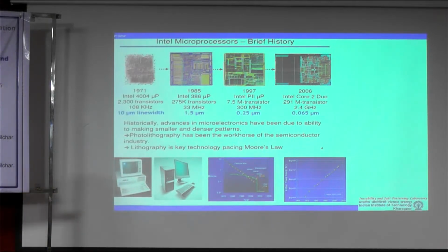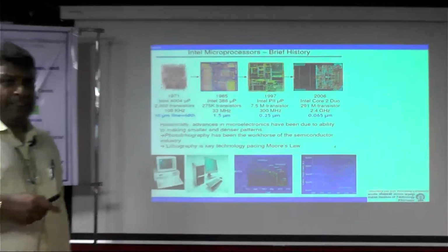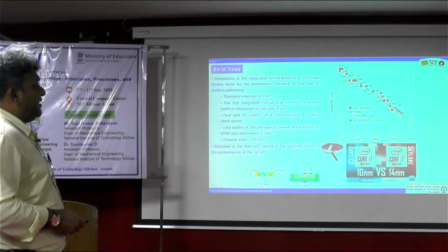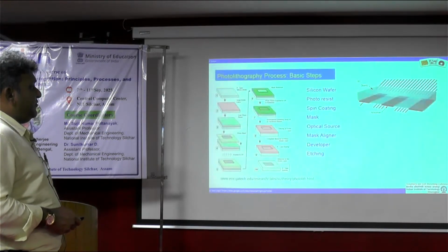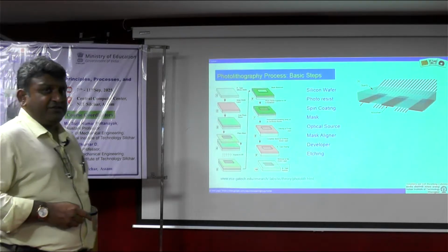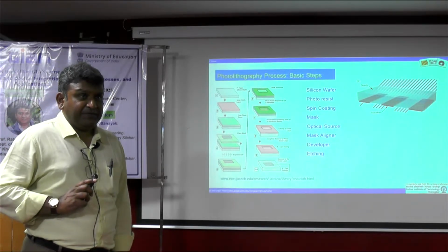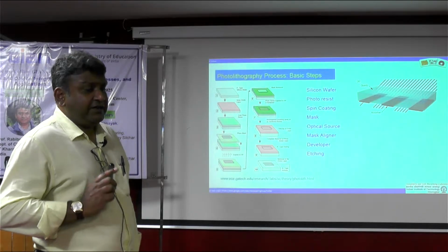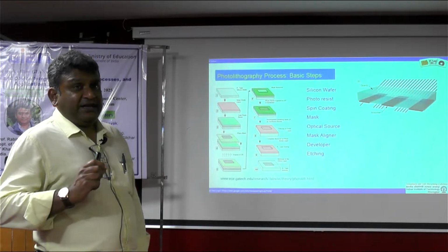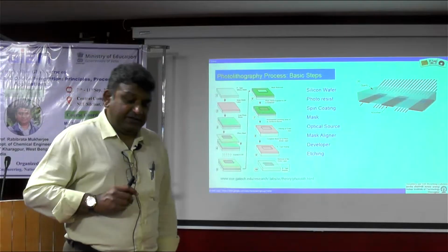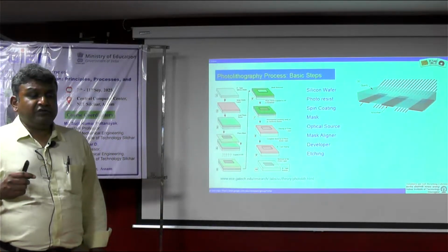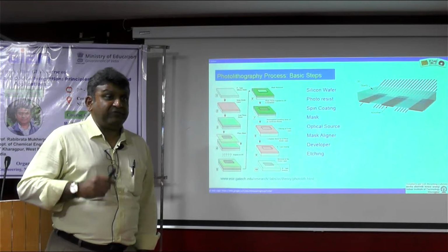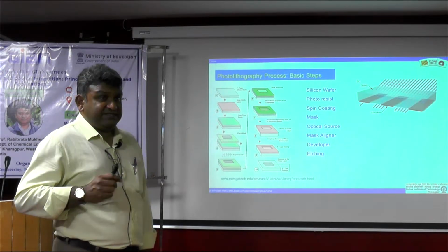Every smartphone has a smart display, right? Touchscreen display, and all these developments. They are all attributed to the development of one major technique. I'm sure it has already been discussed. It's photolithography. So basically, photolithography at the heart of it is light-based. Light is UV light generally, and there can be other types of light. And again, you use a very special type of material, which is actually a polymer, a photosensitive polymer called photoresist.